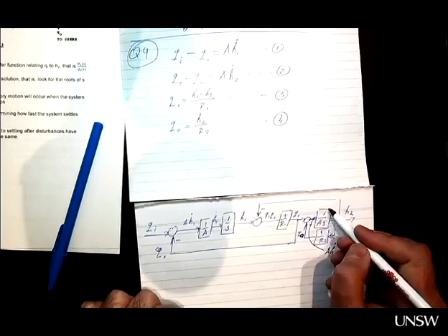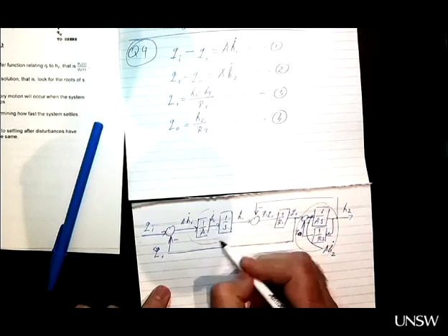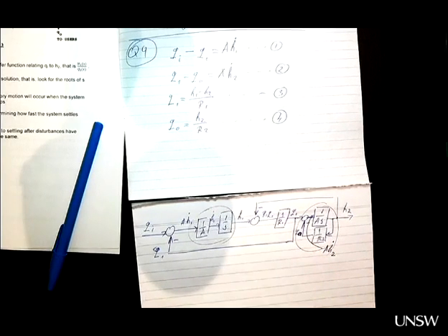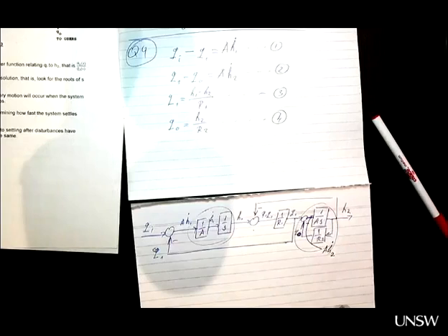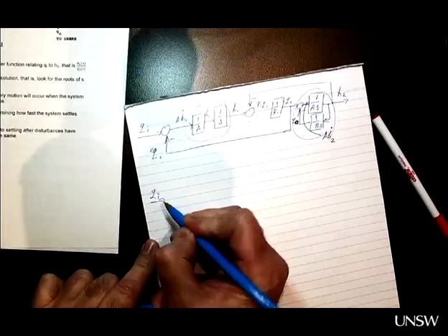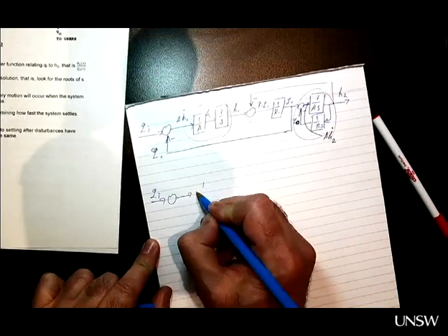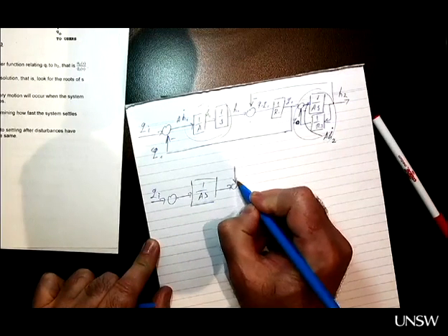Any questions, or should we move to the reduction part of the block diagram? First thing, I think the only obvious thing is this negative feedback loop, and also we have this series configuration. So we can multiply these two and also resolve this negative feedback loop. That takes us to Qi, 1 over AS, 1 over R1.